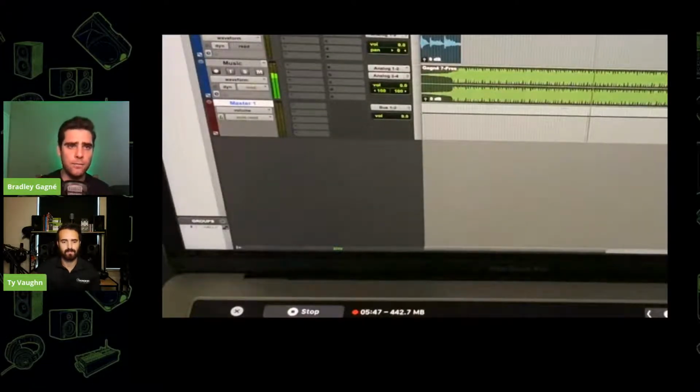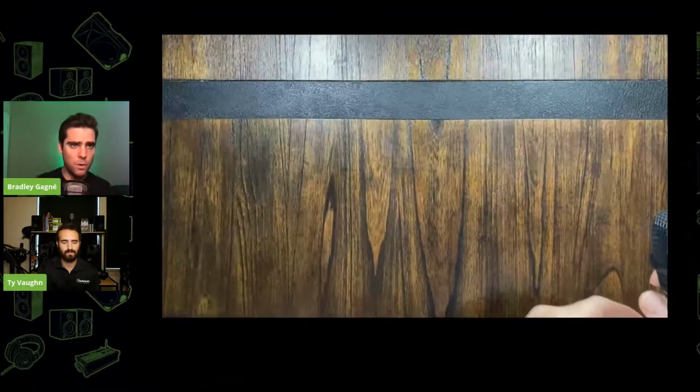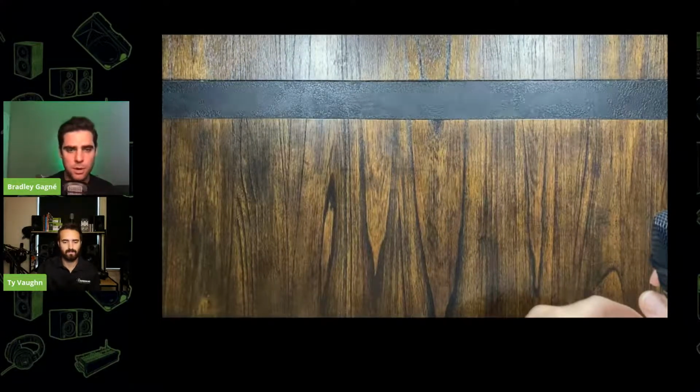But I'd love to show you, Ty, how to do this mix minus setup. This is one of the coolest things. A lot of people get confused when they see a mix minus. I'm going to show you all the stuff that you need. And what a mix minus basically is, is when you give a mix to your listener minus his own voice. And that's where the term mix minus comes from. What you're doing is giving an entire mix of the mixer sent to the phone call or to the listener on the phone